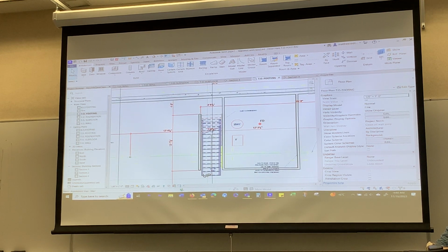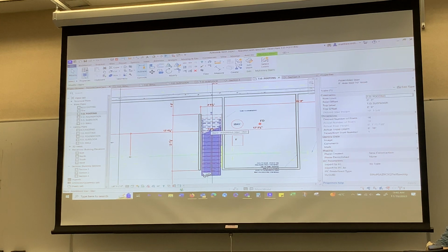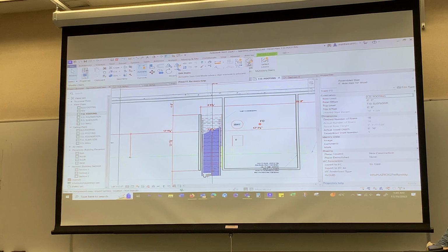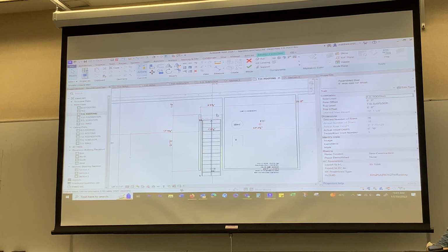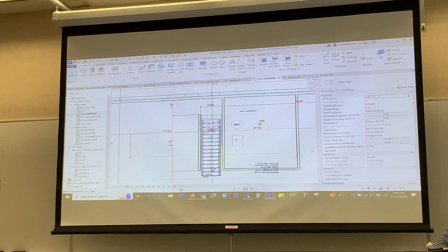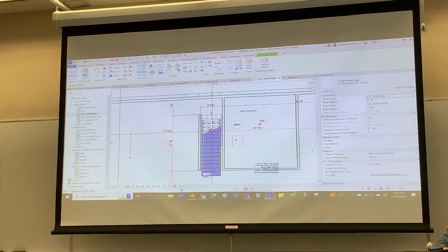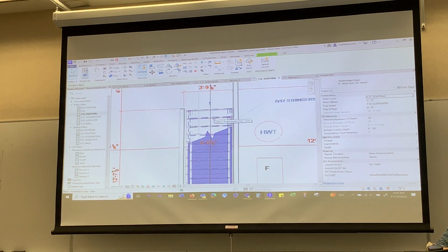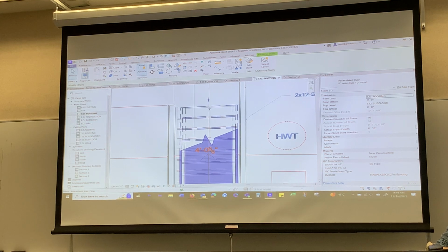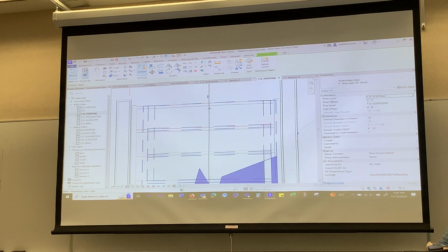Now, if I click on them, click on edit stairs. And now I can drag this, actually no, don't do that. I'm just going to click on them. And I'm going to drag them so that I get that dotted line on that red DWG line. And you can see they're still too narrow, but that's okay. I just got them in position now.